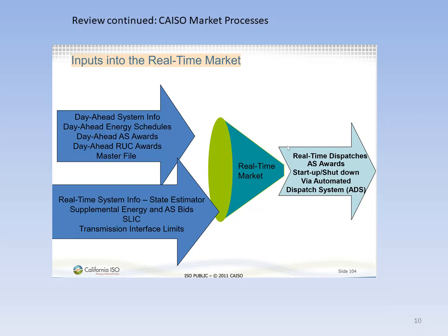Now a few words about the real-time markets, RTM. Real-time unit commitment, RTUC, and real-time dispatch, RTD, were detailed in tutorials 1 and 2. RTUC takes as inputs the load forecasts, supply bids, imports and exports, the full network model, network constraints, and exceptional dispatch instructions. RTUC performs computations and iteratively evaluates feasible solutions and optimizes. It coordinates the startup, shutdown, and transitioning of generating resources to balance supply and demand within its BA. RTUC is synonymous with the 15-minute market. Ancillary services can be procured on this horizon.